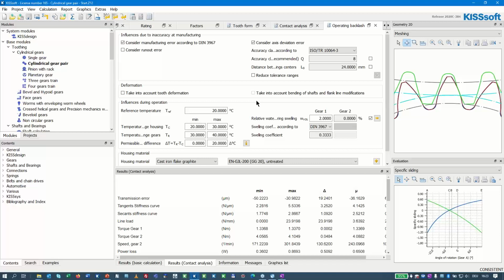That's the condition where the backlash is minimized. You can then calculate it such that it is zero in this condition. And then at the lowest temperature, highest center distance tolerance, and lowest tooth thickness tolerance, you then end up with a given amount of backlash that you can only reduce if you narrow down all tolerances.